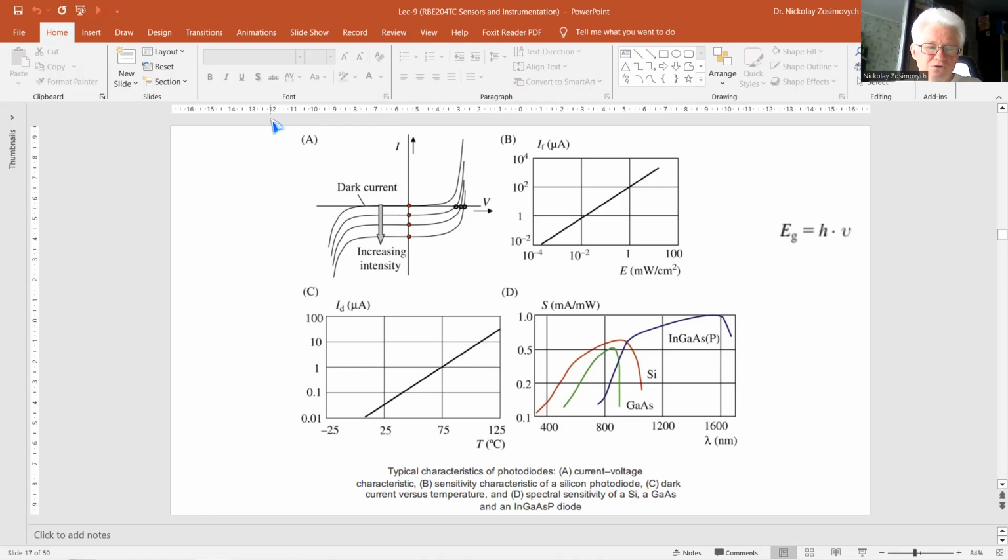Not only light but also thermal energy gives rise to the generation of additional charge carriers around the PN junction. This is exactly why the reverse current of a PN diode is not zero. Roughly, the thermally induced leakage current doubles each 7 degrees centigrade. At room temperature, the leakage current of a silicon diode is very small, sometimes nearly 10 picoampere.